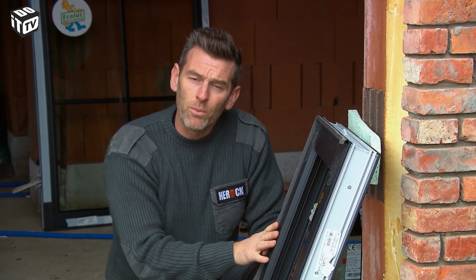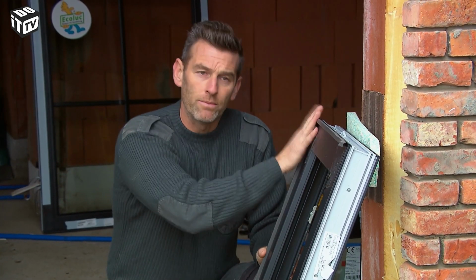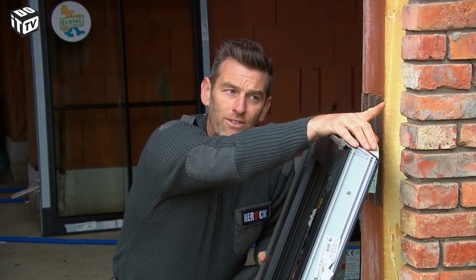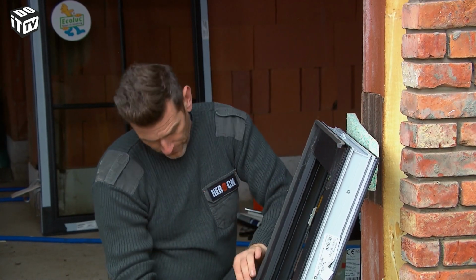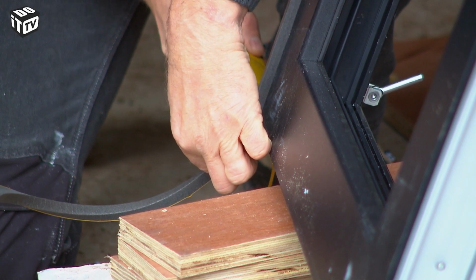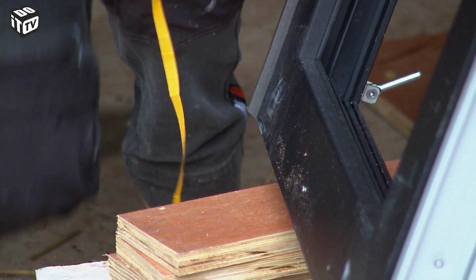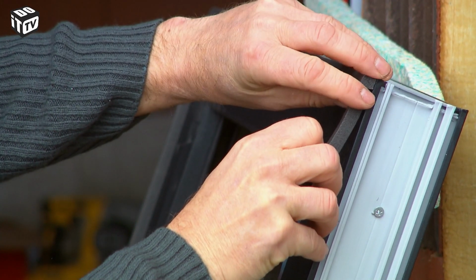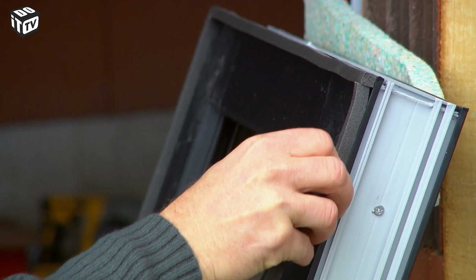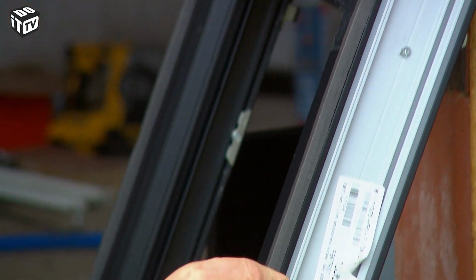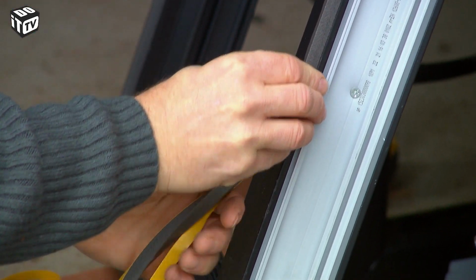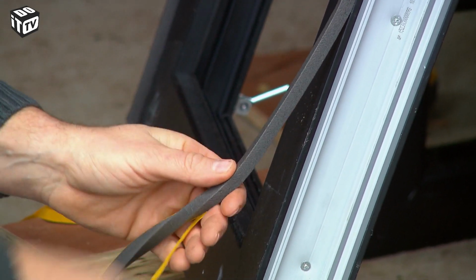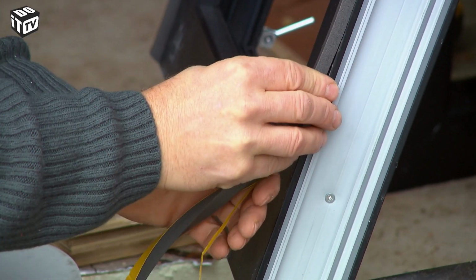I am now applying the Moss band to the frame for two reasons. On the one hand, the strip protects the frame from direct contact with the outer brick, and on the other hand, it gives me the necessary space to caulk the frame afterwards. Trim with utility knife. As you can see, band placement is smooth.